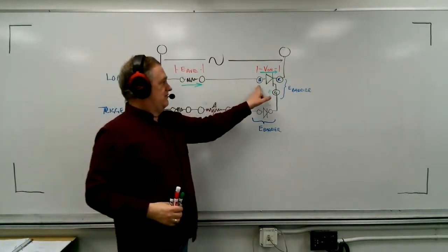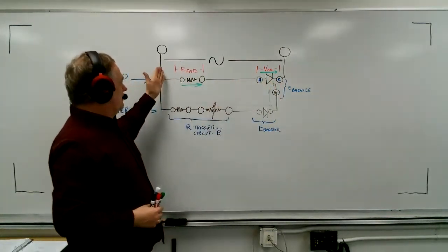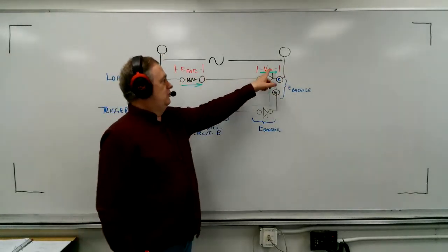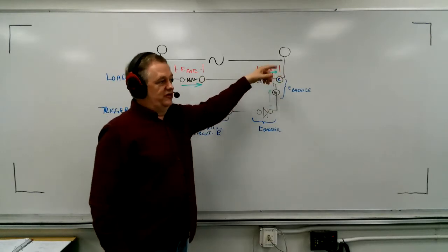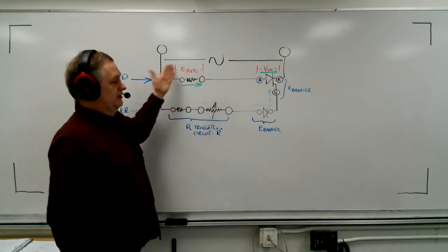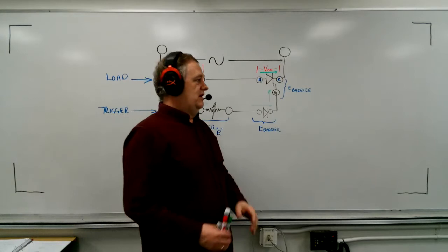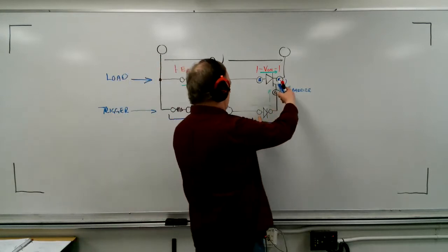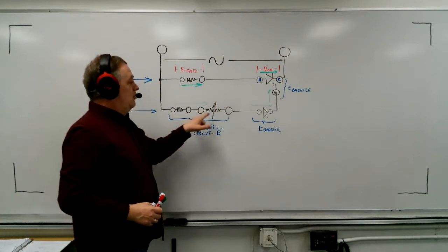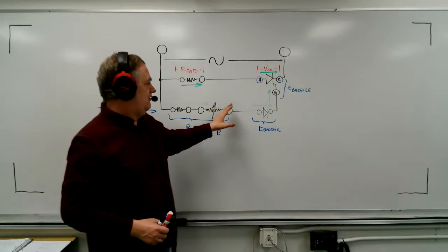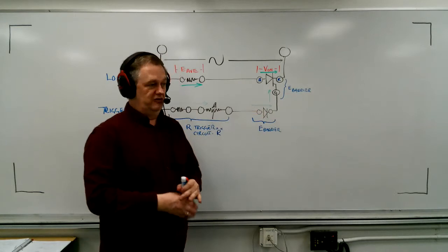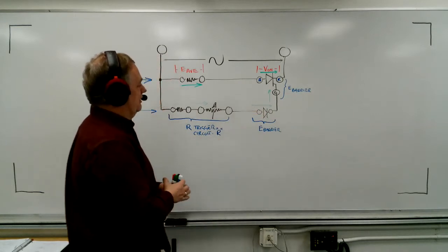Now, the barrier voltage here, when we're talking about this load branch, we don't much concern ourselves with this voltage. It might be 1 or 2 volts, but it's not actually a large factor in what happens with the load voltage. It makes very little difference. Whereas down here, these barrier voltages will make a significant difference in how many ohms, for instance, we have in this circuit. And the reason that the voltage is more significant here is because it's such a small current. It makes bigger differences.